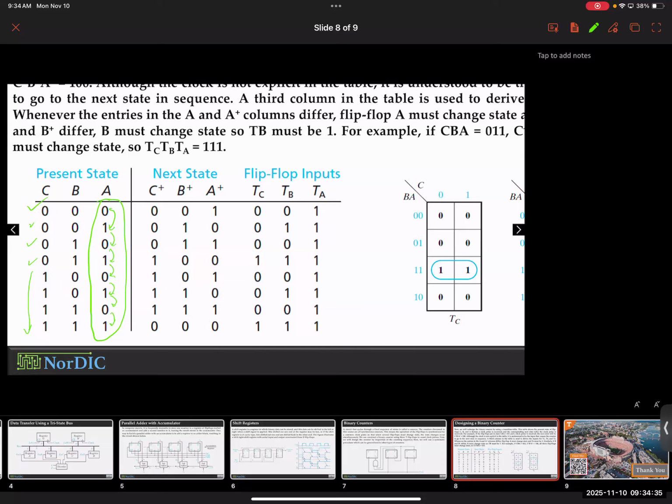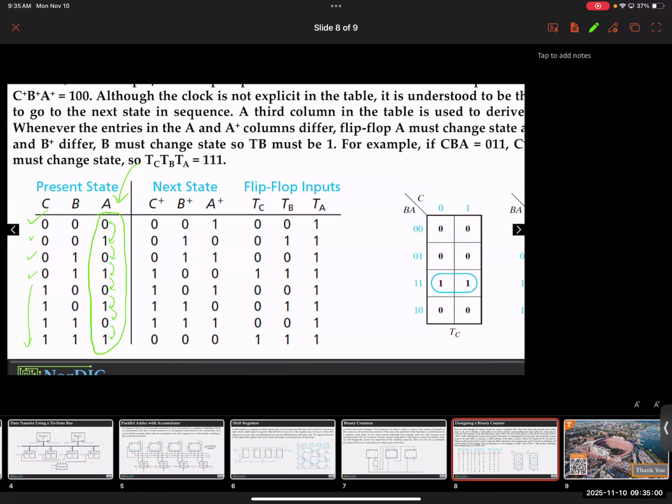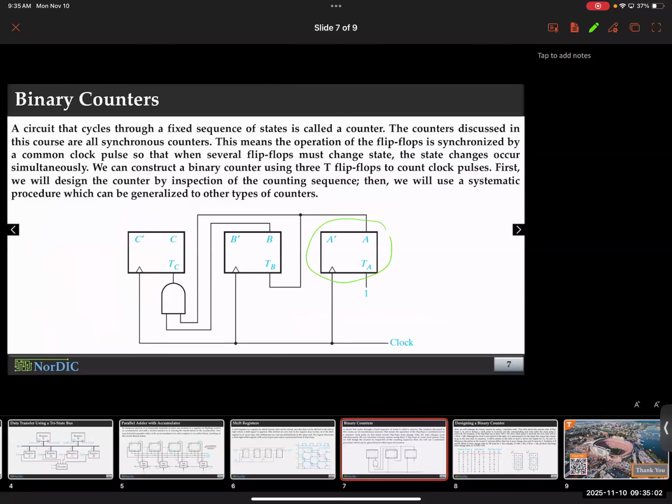Okay? How can I design this? If I try to represent the first bit with a flip-flop, since you have 3 bits, one flip-flop deals with 1 bit. So how many flip-flops do you need? 3, because you're dealing with 3 bits. So for the first bit, the flip-flop that will represent the first bit, it will always toggle. How can you design a T flip-flop that always toggles? Just take a flip-flop, set the input to be 1. That's it. Its output will always keep toggling between every clock edge. Does that make sense, folks? So I'm taking care of the first bit here.